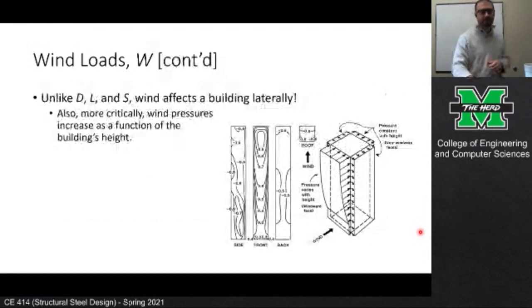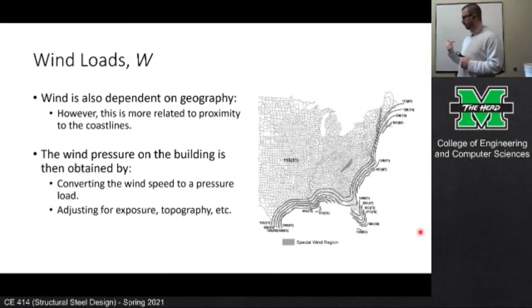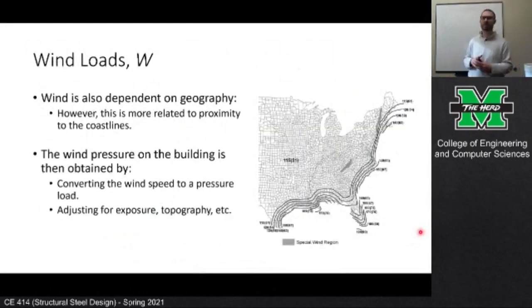One of the other things that pops up with environmental loads is what's called a risk category. So there are 4 risk categories. Let me see if I put those in here. No, I didn't. I'll just give you the brief overview. There are 4 risk categories assigned in ASCE 7. Risk category 1 are unmanned structures like grain silos or abandoned or empty warehouses and stuff like that. And the risk category increases as a function of the structure's contribution to society.